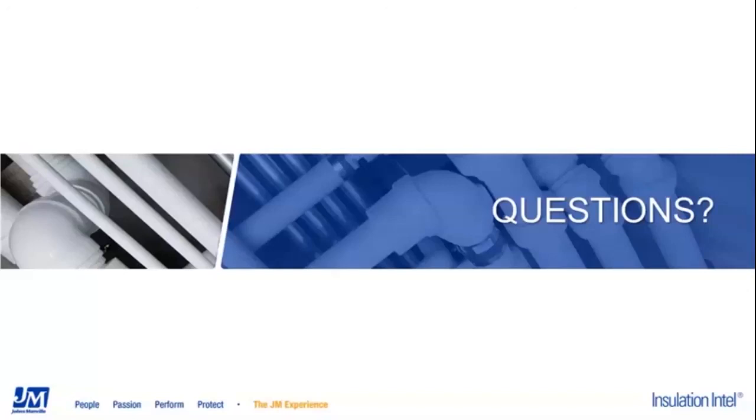Typically, the mastic isn't applied over the entire surface of the insulation unless it's outdoors, and if it's outdoors, it really doesn't matter. Fire safety isn't that big a concern outdoors. Indoors, most of the mastics need a 25/50. So in general, I would say there's not an issue there. With paints, we don't have any control over that.